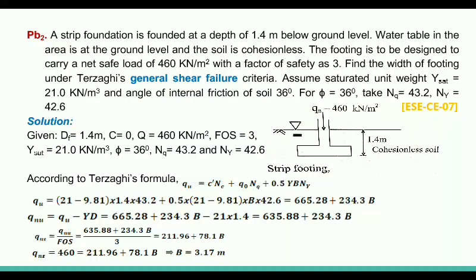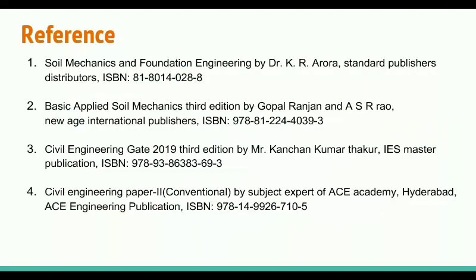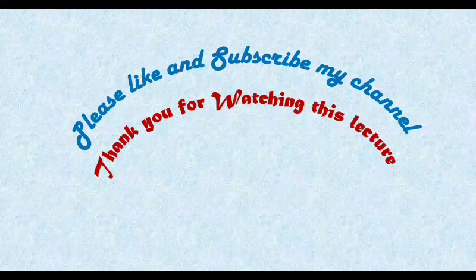In this question, only one thing you have to remember. What is the overburden pressure? Overburden pressure in the case of submerged condition of soil would be saturated unit weight times depth of foundation, right? You cannot write submerged unit weight for the calculation of overburden pressure. Overburden pressure means before the excavation of the foundation, what is the total stress at the base of the foundation where you are going to construct the foundation, right? These are some references that I have taken.